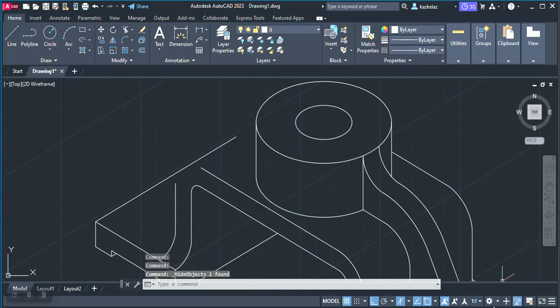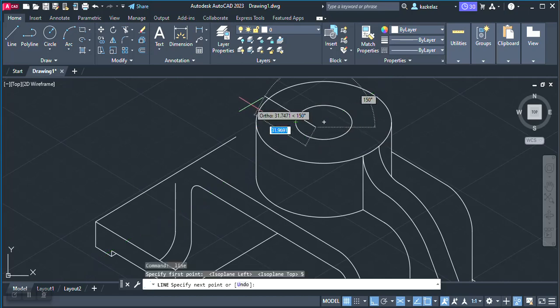Then from that point we step away after the cross appears for intersection. Then we move away by 13 because the center of our 13 millimeter radius arc is going to be there. So then we click there because we know that's a 13. So from there we want this part there and along the line. So something like this here.